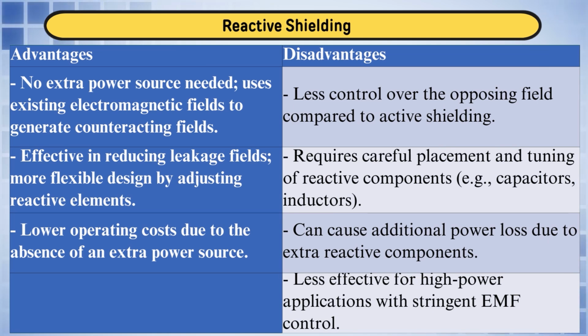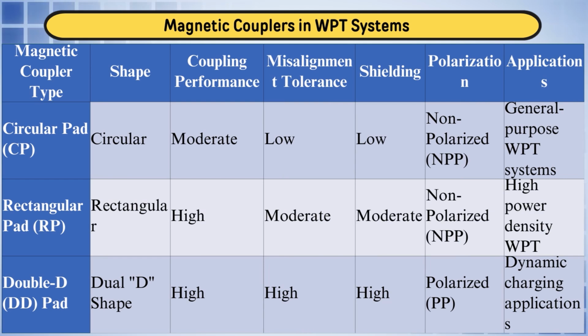Now, we have control techniques for EV charging. The control techniques here we have divided into 4 parts. The first one is linear control. A simple PI control can be utilized for stable charging. People are also using nonlinear control to improve the dynamic response when the battery is switching from charging to discharging and discharging to charging mode.